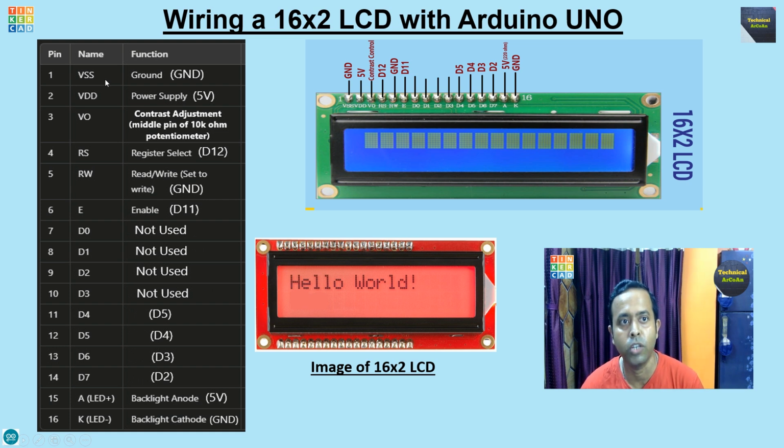Now how to connect with the Arduino. VSS, just connect with ground. Second one VDD is the power supply, 5 volt. V0, which is contrast adjustment, means we are using a potentiometer where the middle pin connects with that particular pin, and it should be a 10k ohm potentiometer, right? The fourth pin is RS, register select. In my sketch, I connect this pin with digital pin 12. Okay. Next is RW, connect with ground.